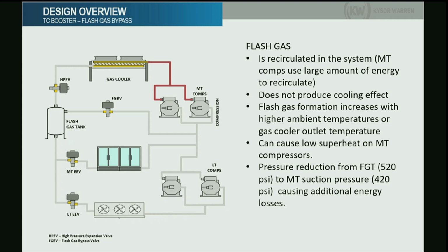So at that point, we have high pressure and temperature vapor going into the gas cooler. The gas cooler operates very similar to the condenser. It has fans, it has coil. Basically, we'll be rejecting the heat from that vapor to the ambient. So this operation is similar to the condenser, doesn't change. And from here, we have a cooler vapor coming out of that gas cooler and going into the high pressure valve. But it's only vapor, right?